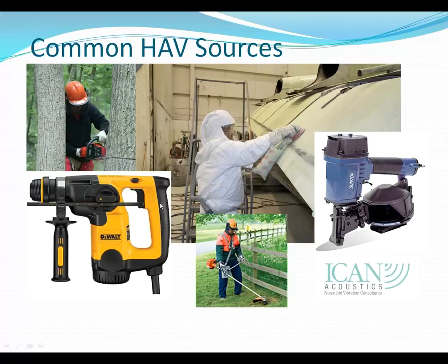Again, with a lot of the manufacturers, this isn't an example of one, but you're always concerned with the handles. You're concerned with where the operator holds the particular piece of equipment, and that's where you attach your accelerometers. Local authorities have a number of people using brush cutters, and again, they have their hands firmly on a machine that's mechanically connected, and a certain level of vibration is induced into those handles all the time.